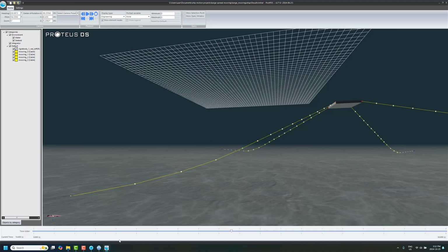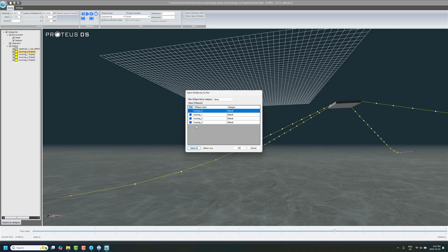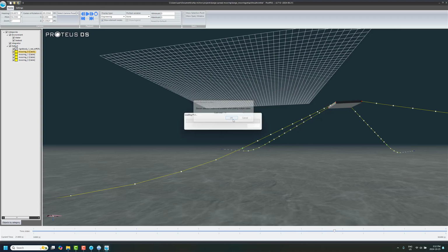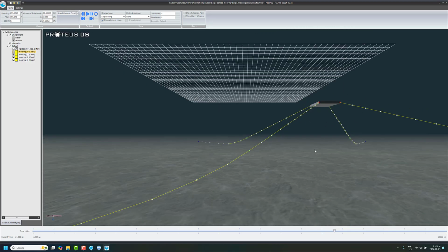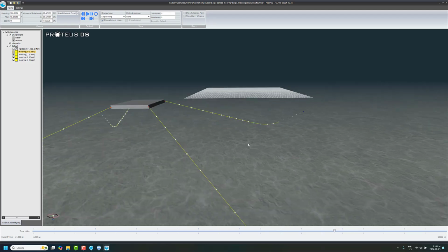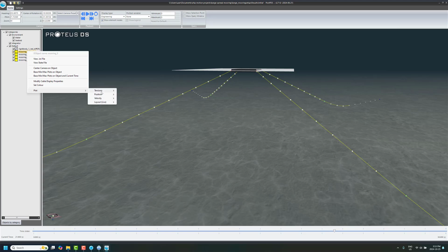So this is a nice comfortable distance off there, and then if we click on plot tension versus time, in fact you can click on all the moorings to see what they all look like. We want to look at node 1, and we're getting to about 33 kilonewtons of pretension, which, depending on what you're doing, might be a good amount, a little bit high, or a little bit low. The higher the pretension, the more it's going to be restricted to staying in one place, and it really depends on the condition of what you're looking at. So we could, this settled actually really fast.